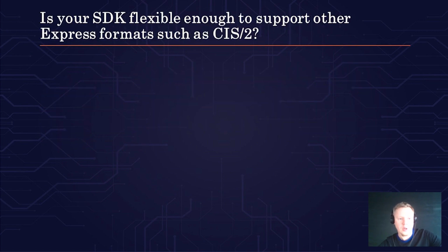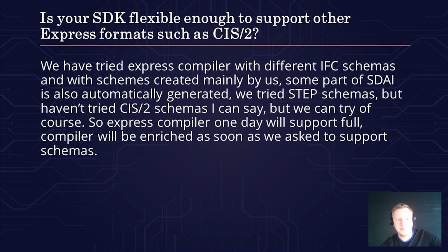The next question: is your SDK flexible enough to support other Express formats such as CIS2? We have tried the Express compiler with different IFC schemas, and with schemas created manually by us. Some as a part of the SDK are also automatically generated.